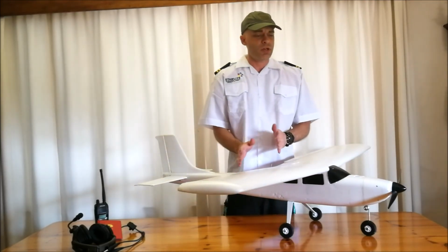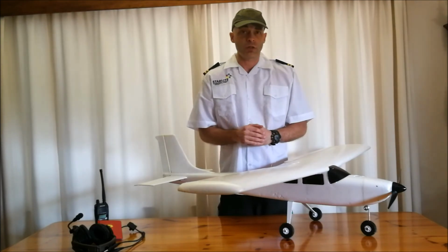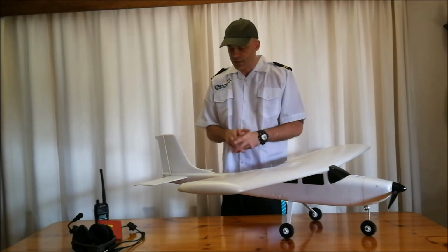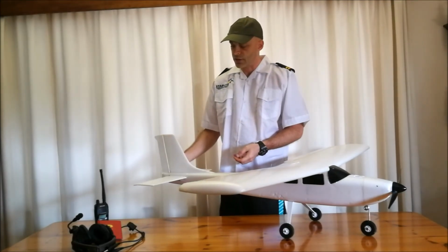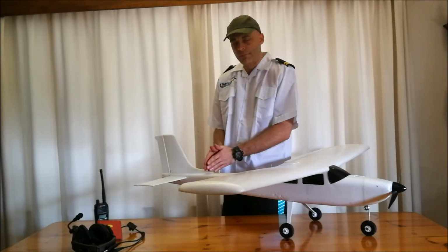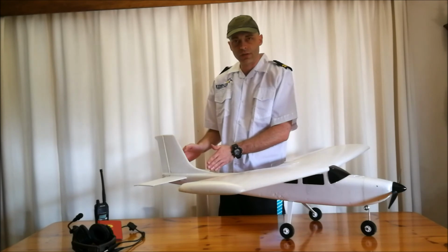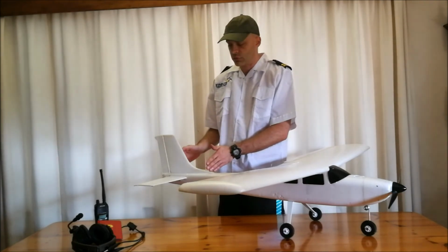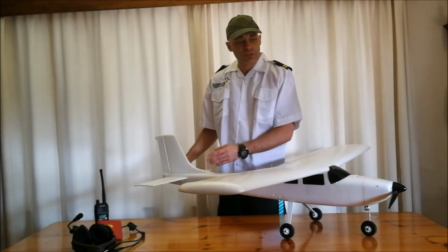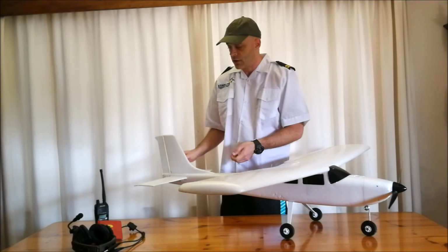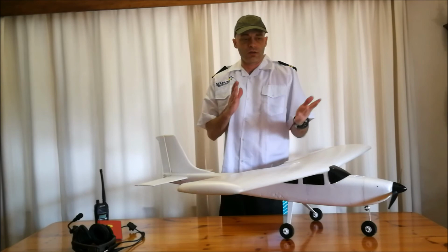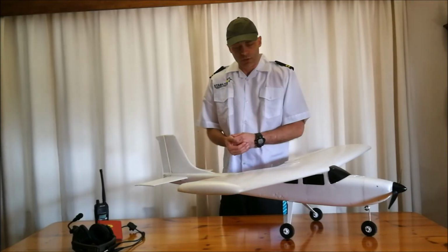And so you generally want to have the payload, or most of the weight, as much to the front as possible. The reason is that if you've got a control surface like your elevator that has to move upwards and downwards, and the center of gravity was towards the back, the arm length would be so short, and therefore also the moment so small, that the amount of force the pilot has to put on the control stick to move these elevators up and down would be a lot, and it would be very difficult to make the aircraft pitch upwards and downwards.